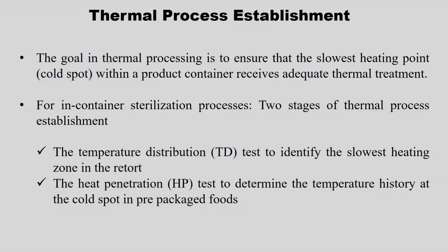Good morning all. Today we are going to see temperature distribution and heat penetration studies for thermal processing of food. Before going into that, we will just see what is the motivation for us to do the temperature distribution and heat penetration test. The goal of any thermal processing is to ensure the slowest heating point, which is nothing but a cold spot within a product container, receives adequate thermal treatment, right.